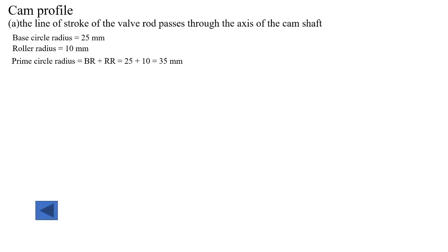Now we will see the construction of the cam profile when the line of stroke of the valve rod passes through the axis of the camshaft.